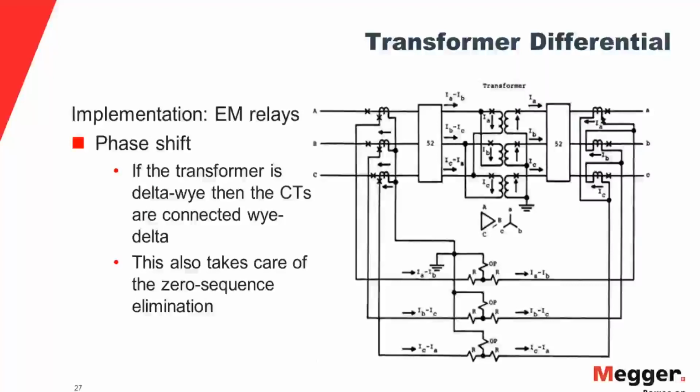And also, you have to make sure that the delta connection increases the value of the phase voltages or currents by 1.732 factor. So you have to consider that as well when you're calculating the CT ratio of the differential function.